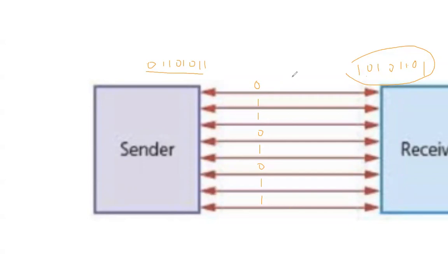So that's why, if you are using parallel cable, and we do need to use parallel cables, I'll explain why, you have to keep the length of those cables short, because if you keep them short, then the chances of skewing are minimized. A second aspect is also that these cables are expensive. So if I have long cables, that means more cost. If I have shorter cables, that keeps the cost down and the chances of skewing also down. So that's one aspect of what the problem is.